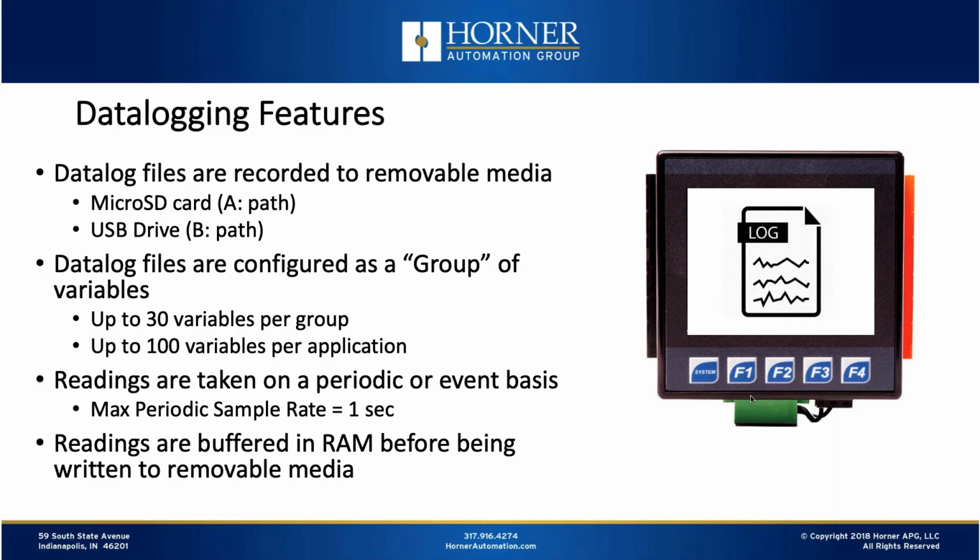In general, we typically recommend microSD. It's less of the wild west out there in terms of the quality of the USB flash drives, so we generally recommend microSD. It's also really good in terms of temperature specifications. It doesn't have a lot of mass, so it's not really affected by things like temperature and vibration, even though you might think it would be. USB is a little bit more susceptible to the environment.